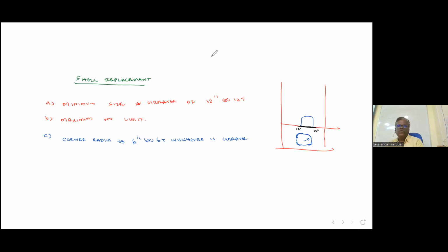Then how will we do the welding? First weld this area, all butt welds. Finally we will weld the horizontal joint. So when a replacement comes along the horizontal joint, you have to cut the existing horizontal weld 12" beyond the size of the plate, both sides. First complete all other welds, and finally weld the horizontal joint. Is it clear?